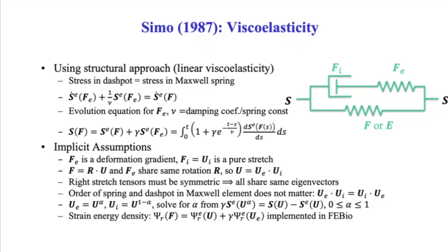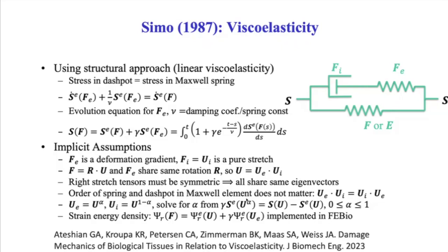This is relatively recent, meaning those of you who might be using viscoelastic models in FEBio may not have realized it, but in the past, if you requested to plot the strain energy density in a viscoelastic material, it just returned 0. Now it doesn't return 0 anymore. It returns this calculation. But there are a number of constitutive assumptions inherent in this calculation, so I wanted to share that with you. Okay, all of this is great, except that the problem is, yeah, so the details of this presentation are in this paper.